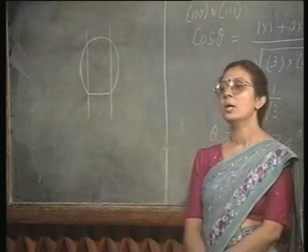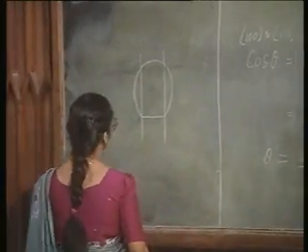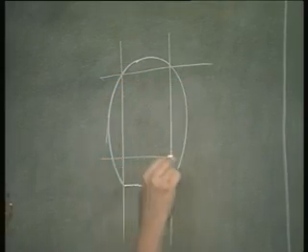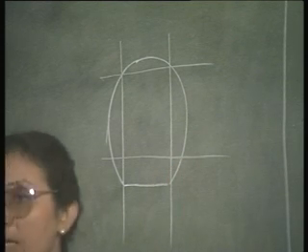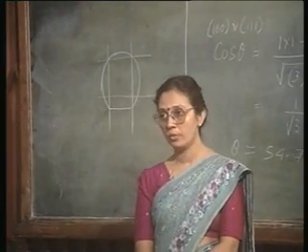Fortunately, in 1 0 0 wafer, we have an advantage, that is the 1 1 0 lines meet at a mutually perpendicular direction, and you can cut out rectangular chips from a circular wafer.